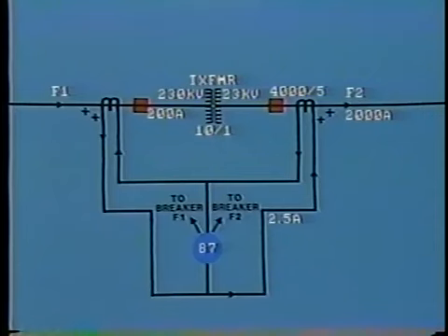And in this case, the chosen CT ratio will be 400 to 5 to give equal secondary current, 2.5 amps. However, in practice, there are transformer losses and also losses associated with the CT secondary leads, which may differ considerably in length due to station layout.